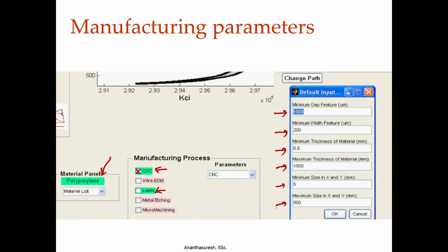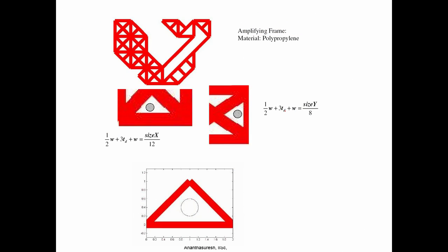It can be laser, it can be CNC, then accordingly the mechanism design can be redone so that manufacturing aspects are obeyed. And we also said strength can be obeyed because there is a maximum stress; you can click that button any time and see what the maximum stress in the mechanism is. So this is the philosophy, where you have the interactive thing where we can change.